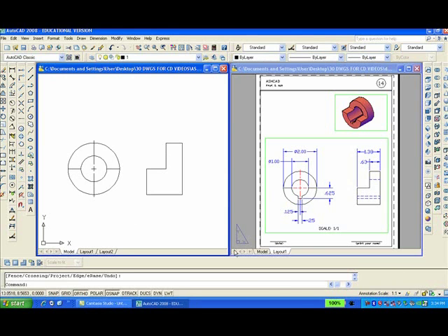Now you want to offset. O enter, 0.125 enter. This line in that direction. Repeat the command, and there. Also you can offset, enter, 0.625 enter. Offset 0.625 enter. Select this center point here, center mark there, and bring it down here like that, and then zoom in.